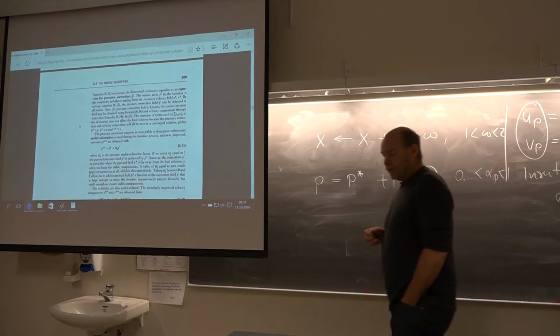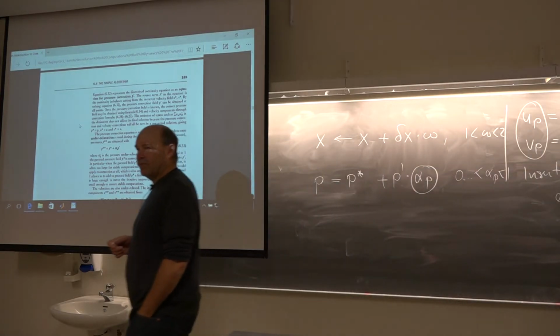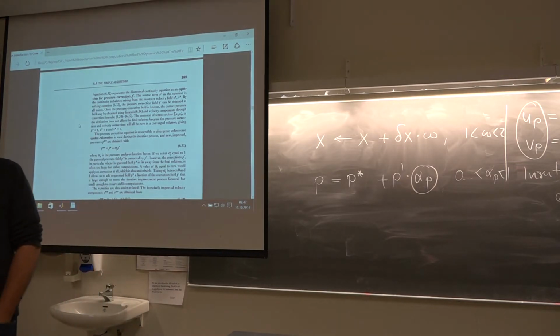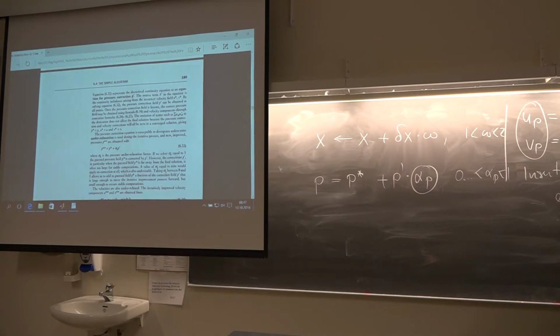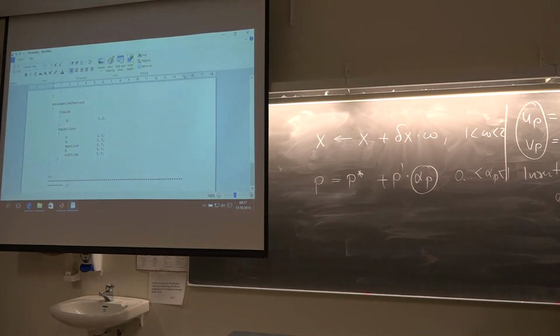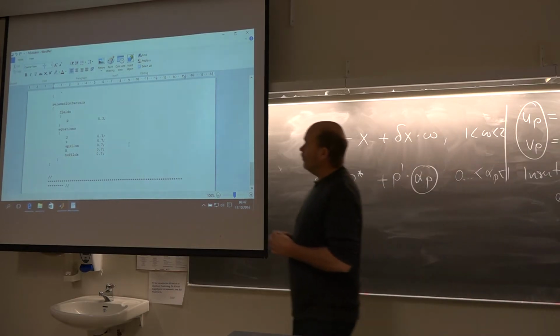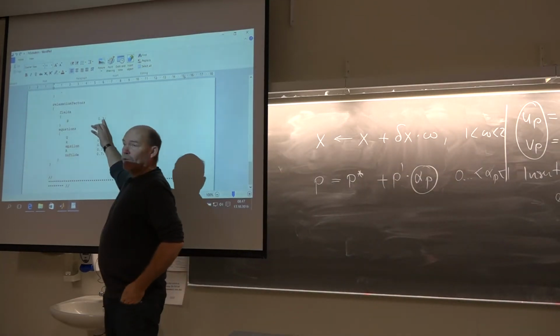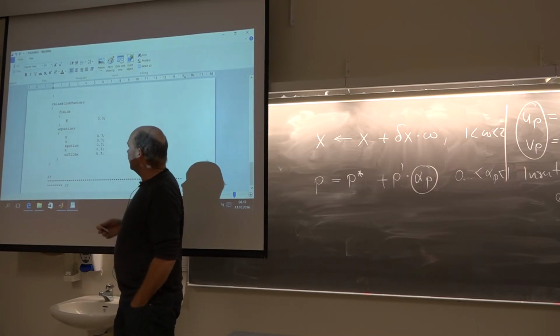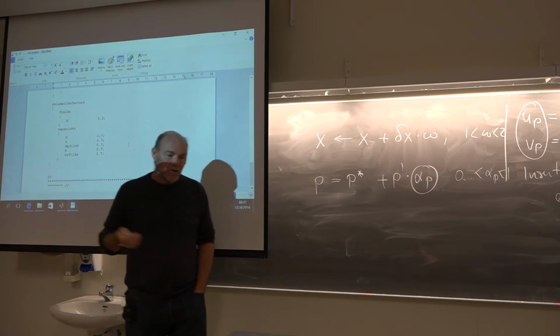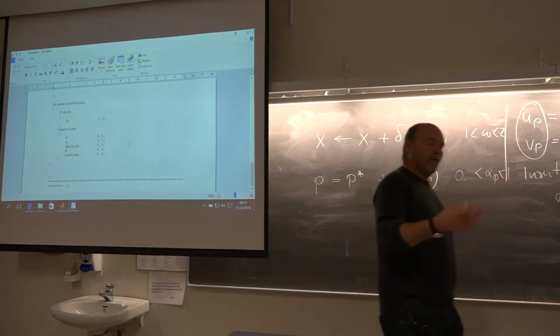Try to use a number bigger than 1 to speed up the process. Things will explode in your face. Just try it. These numbers are something that we have as an input option into the code. If you can see here, relaxation factors for the pressure, they use only 30%. For the different velocities, they use 70%. So typically different from pressure to the other variables.